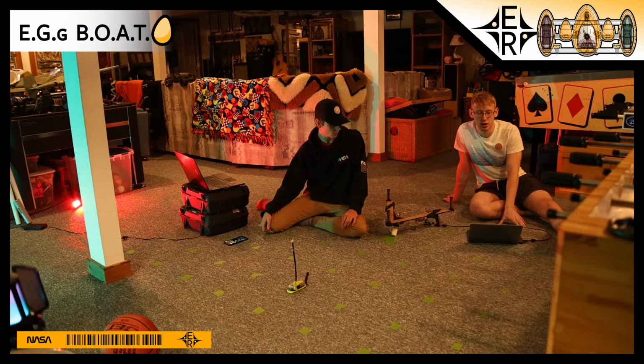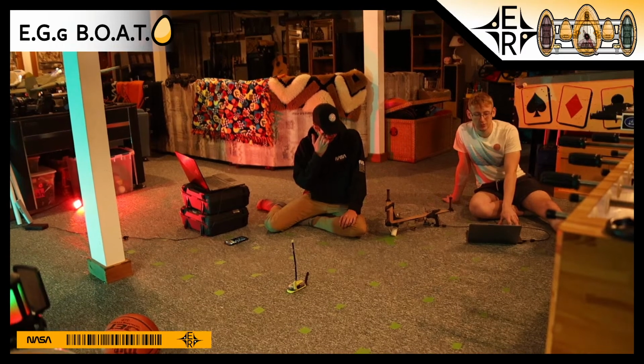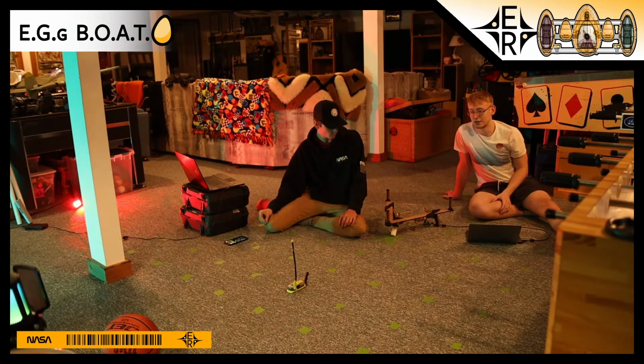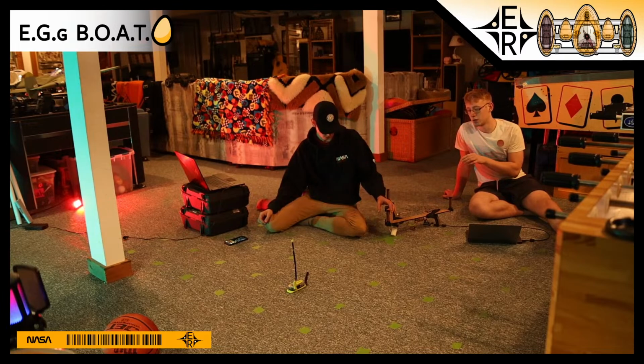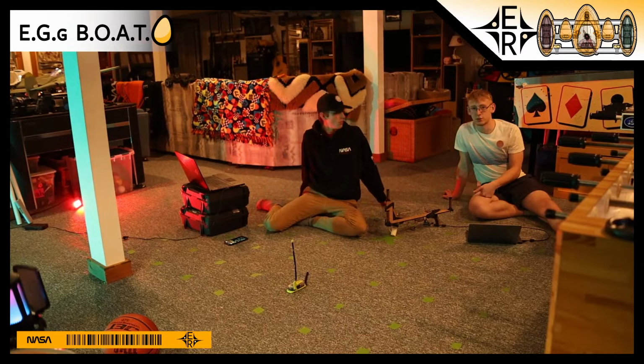So to get an approximate voltage output, you can multiply by around 5 millivolts. So we're getting close to 0 volts and about 3 volts, which is actually because, while we're powering EGgBOAT in general on 5 volts, all the circuits take that 5 volt signal and convert it to 3.3 volts, because that's what all the chips run on.